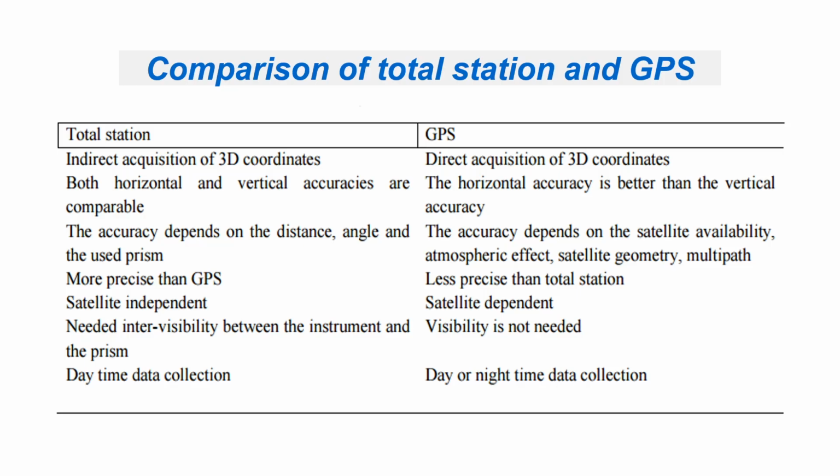It is satellite independent, so we can use it indoors and underground. It needs intervisibility between the instrument and the prism. In my opinion, it is a disadvantage, because GPS equipment does not need intervisibility between stations, or daytime data collection.